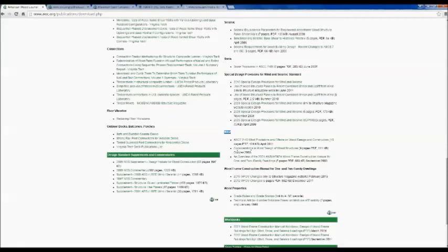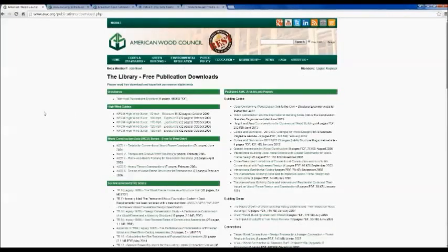All right, and then this paper right here, the second one in the list, is called Consideration in Wind Design of Wood Structures, from October of 2003. So it's over 10 years old. That's when we got that interpretation many years ago from the Wind Load Subcommittee, and that talks about the difference between designing studs for bending only using components and cladding load, or combined bending and axial using main wind force wind loads for the bending portion. And that's pretty clearly spelled out there in that paper. Shows an example, and that's something that once folks realize that we can do that, really saves a lot of time, one, but allows you to use stud sizes that we traditionally use for design.